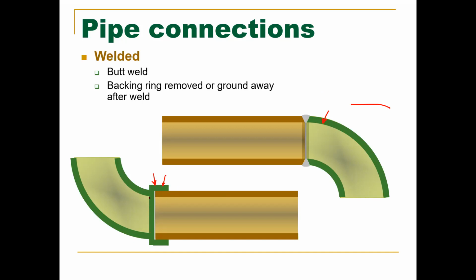You'll never really see it in the opposite direction, because if you do, then you're going to be losing material on the inside of your pipe, and then you're going to be slowing down whatever fluid is going through. Plus, if you have just a straight wall there, you're going to have eventual wear. It'll erode it.